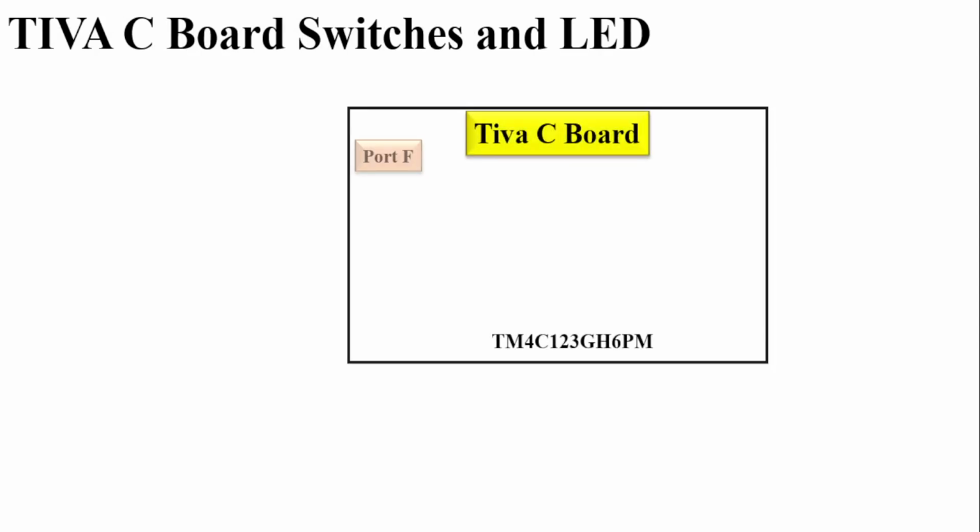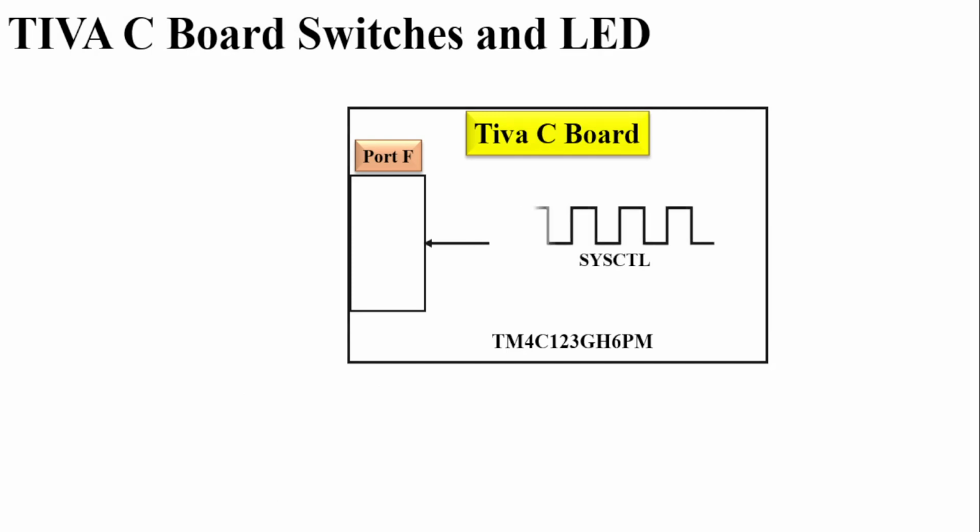Now let us briefly understand the concept. So we have port F. To activate port F, we first have to provide the system clock using sysctl.